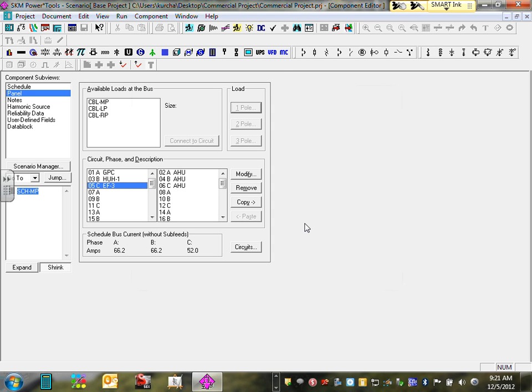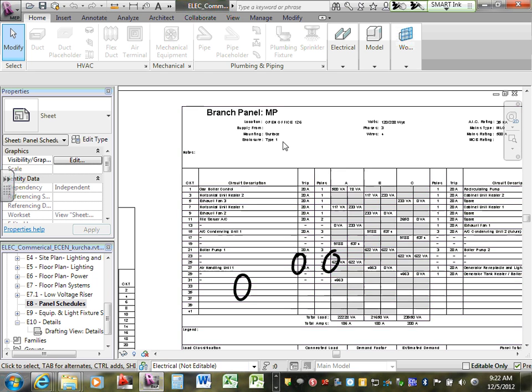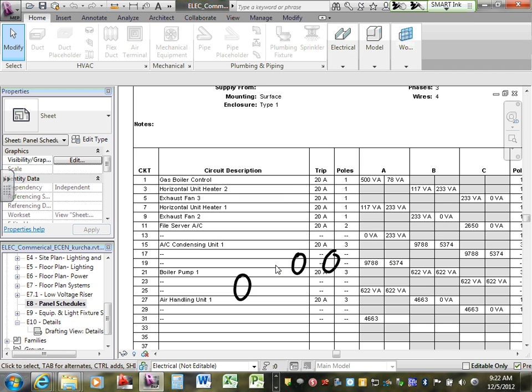You have to tell them what panel to put it into, don't you? We're already in the main panel. Doesn't it have to be highlighted saying it's connecting to it? No, it's already done. We're already in the main panel. You're building the schedule, guys. Can you guys see that? I'm in the main panel, Jimmy, and I'm building this schedule inside it. Darren, good? You know how to build these? Either single pole, 2 pole, 3 pole, put the load and overcurrent protection device.